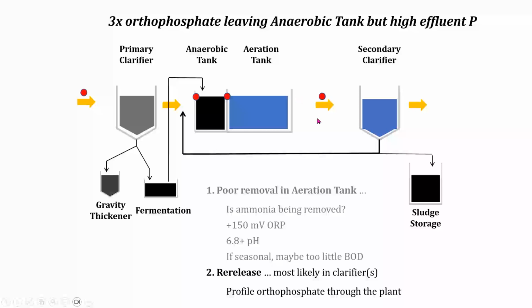There's a facility in Athens, Tennessee, an oxidation ditch, that in the summer, right here, his phosphorus is like 0.2. Okay, what's that tell me? That tells me all of this is working. His phosphorus right there is 2.0. Well, he's losing phosphorus in his clarifier. It's coming out of his sludge blanket. And then we go further.